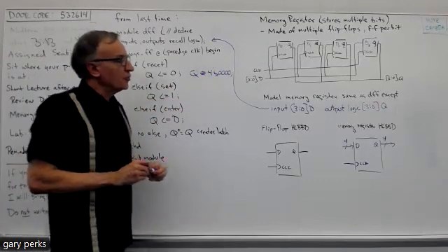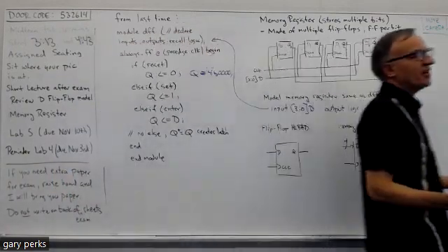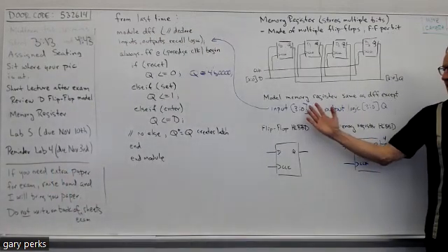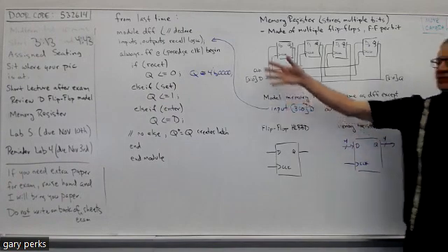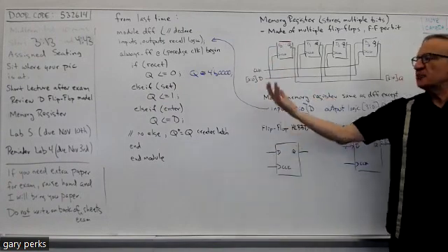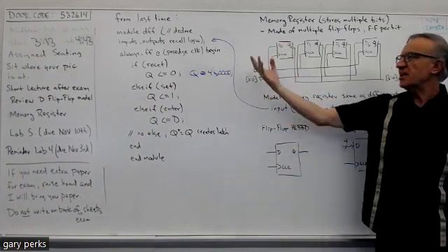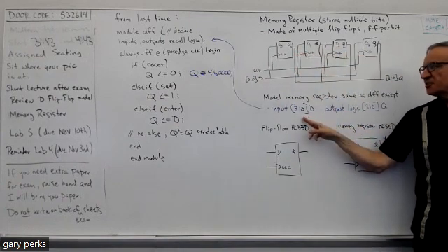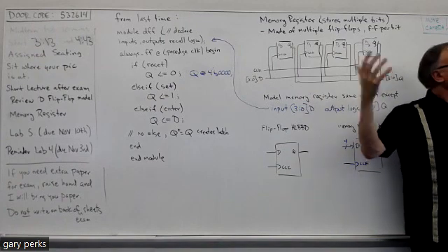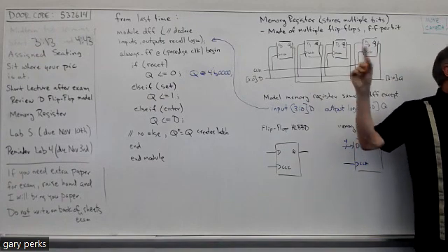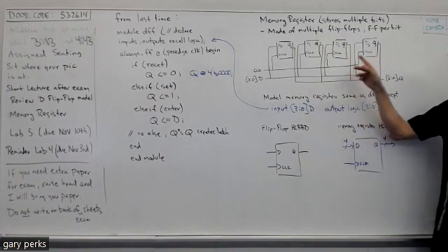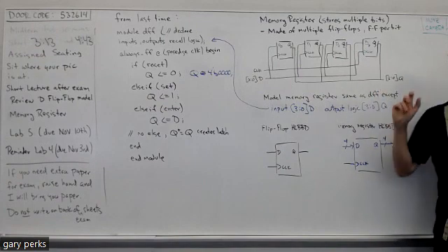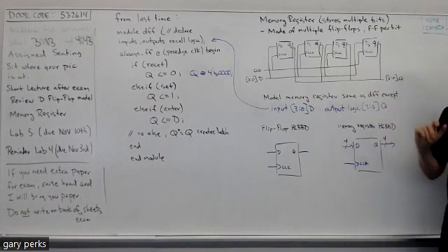Okay, so what the software will do, what Vivado will do, is it will recognize that you want to make a register, that you just want to replicate these flip-flops 4 times because it understands that a register is flip-flops with their D inputs connected together and their clocks connected together and their Qs that come together. So the software will do it for you.